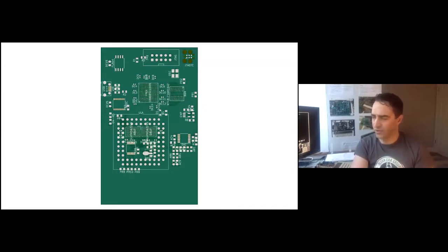So that's those 2 BGA chips inside the ULA socket there. What else have we got for audio? I was considering just making this a GPIO, but I thought, what the hell? We've got some room. Let's add a DAC. So I put something like a 24-bit DAC on there for our Electron's little 1-bit output. That's it in the bottom right.